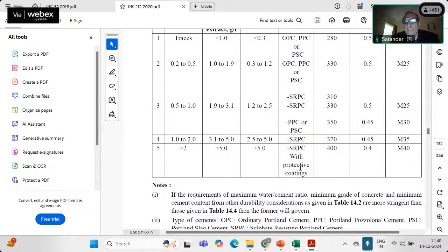If you do not cut the joint within 1 day or 2 days, due to warping, cracks will occur. If we add 35% as per IS code, yes, we should follow IS code. But that IS code is applicable everywhere, for flooring, so we have to think strictly. So we have allowed only 20-25%. However, in the case of bridges, because formwork is there, in our case, it is an exposed structure. So we cannot allow more than 25 as per our mutual discussion.